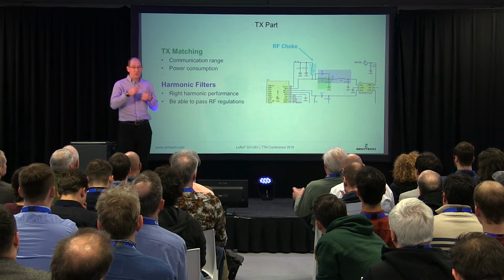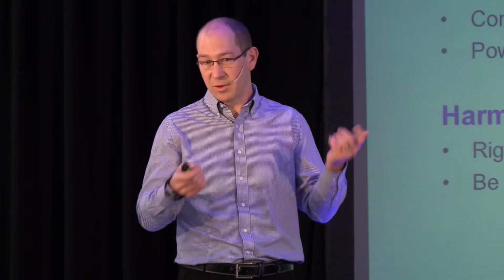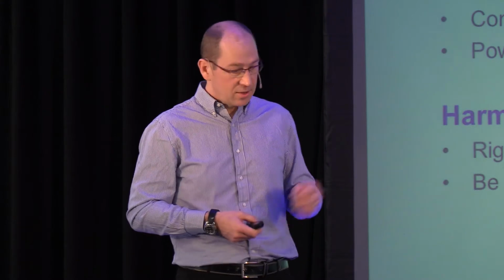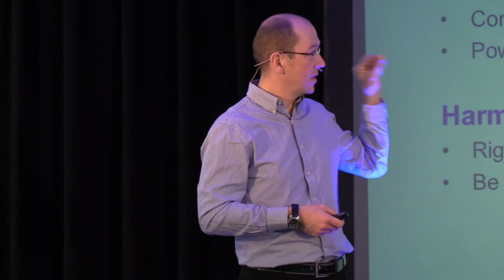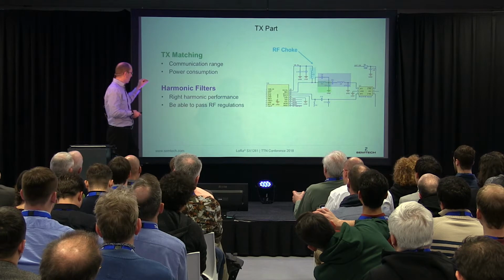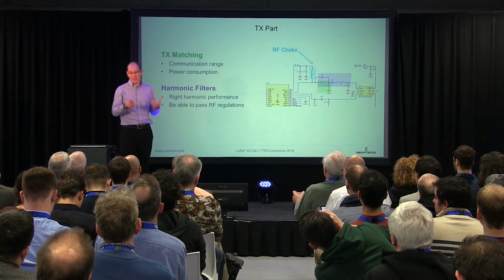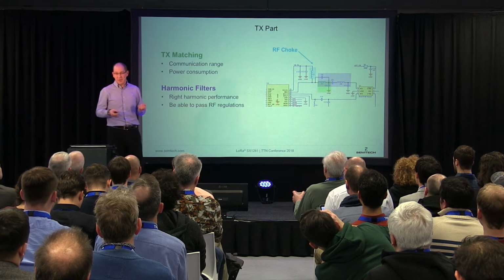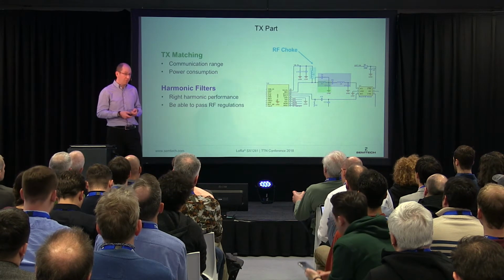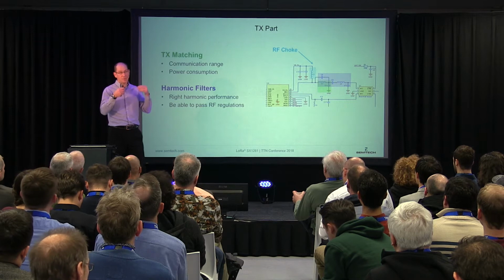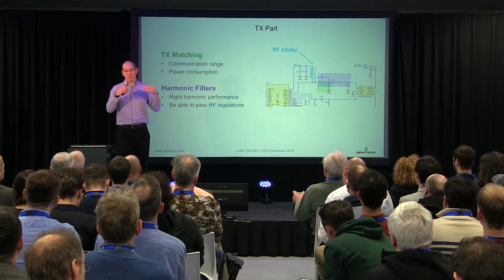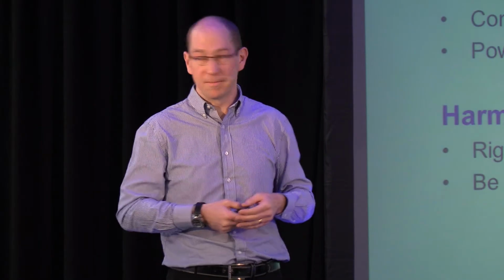But also, you want to minimize the power consumption. You don't want to burn your battery after 1 day of usage. So you have to present really the right impedance to the PA. But every PA also generates RF noise, and this RF noise can be a problem in your application. You have to ensure that your RF noise does not exceed a certain level.